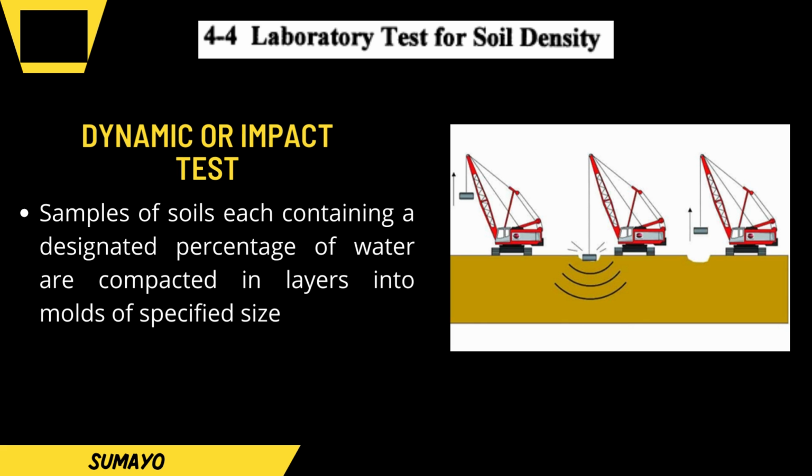The sample is compacted by applying a number of blows from a free-falling hammer of prescribed dimension and weight with a flat circular face. And then the peak of moisture density values represents the standard density. The AASHTO test may be applied on that portion of the soil which will pass the number 4 sieve or all that passes the 3/4 sieve.